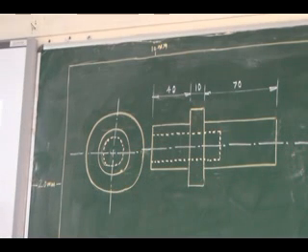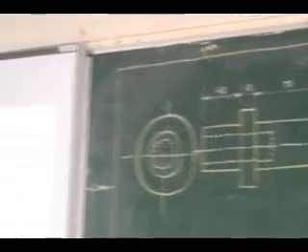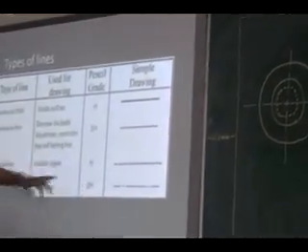So clear? For representing the center lines, normally center lines will be represented for cylindrical objects. Right? So that will be shown as a long chain line. It is a thin line, drawn in 2H pencil. It will be like this.